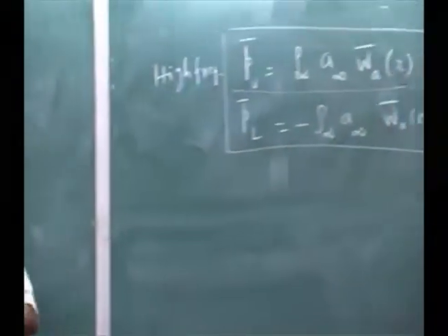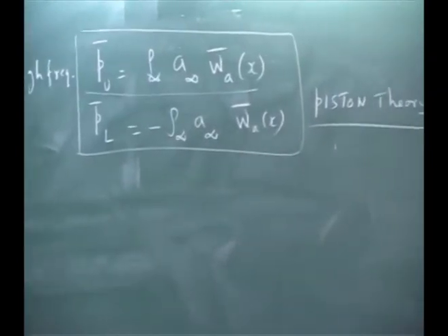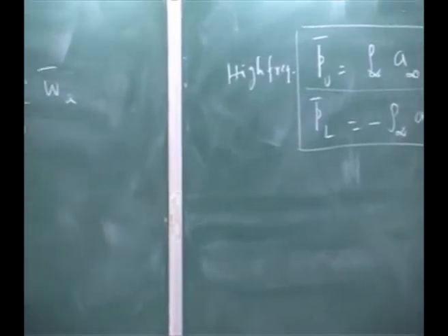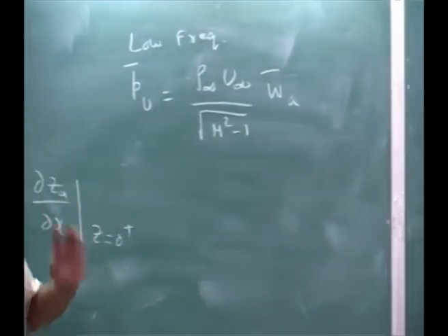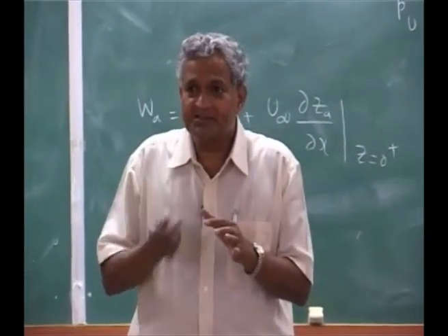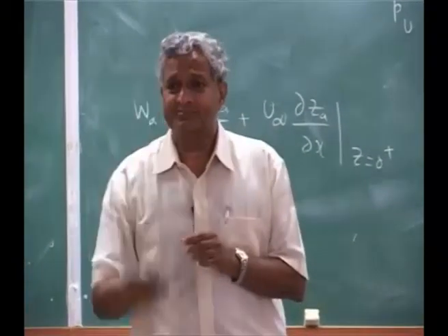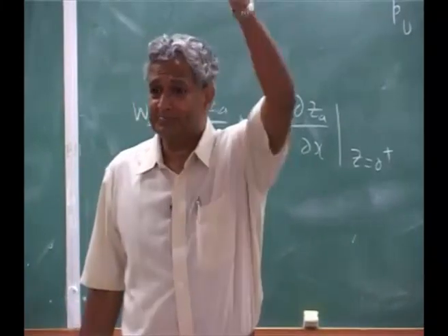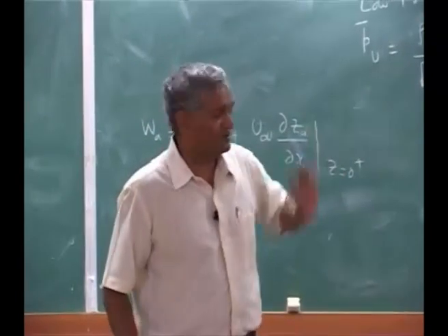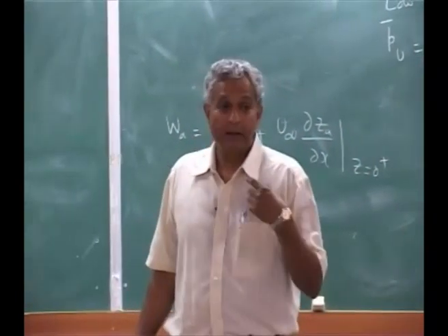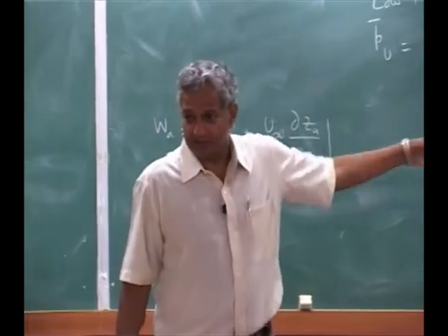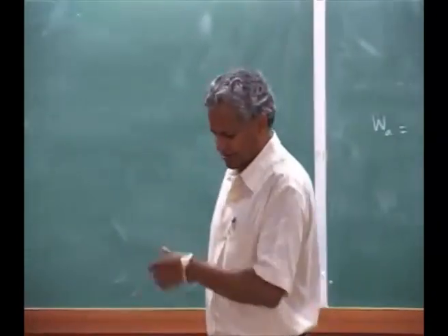Even if you have a panel in supersonic flight, the panel will vibrate. And the piston theory essentially means each small area is considered as though it is a piston, a long piston. And you just move whatever is the pressure there, that is the pressure given by that expression. That is why it is called the piston theory. Okay? A very good approximation, because I have that derivation.